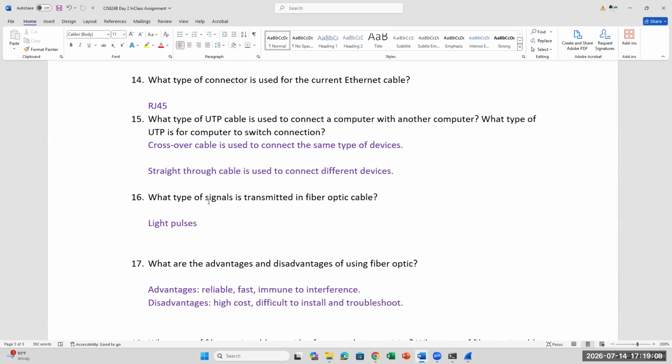Now, if you look, they are twisted, right? These are twisted copper pairs. You have to untwist them, and then you need to arrange them by color when you insert them into the connector. So for the UTP, there's no foil underneath when you take the plastic off.